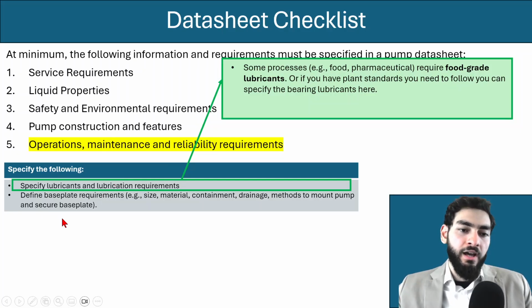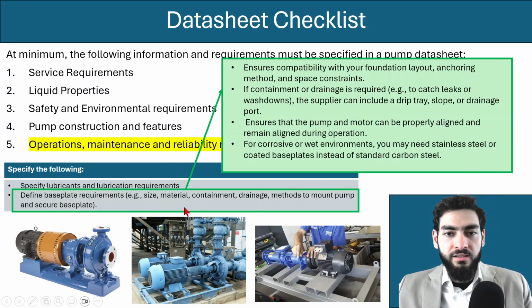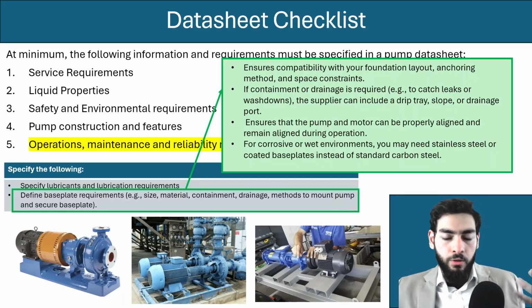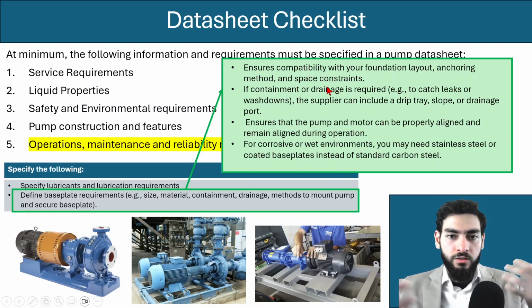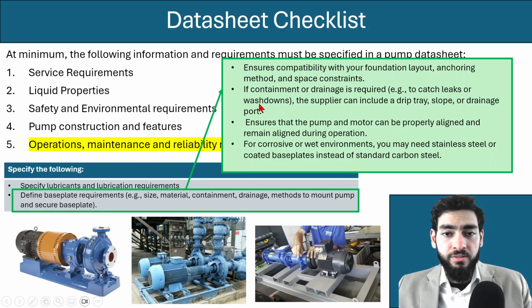Also, you want to define your base plate requirements. So this ensures that the pump foundation, the pump frame, is compatible with your building foundation layout, and if there's any anchoring method and space constraints, you want to communicate that with the pump supplier.